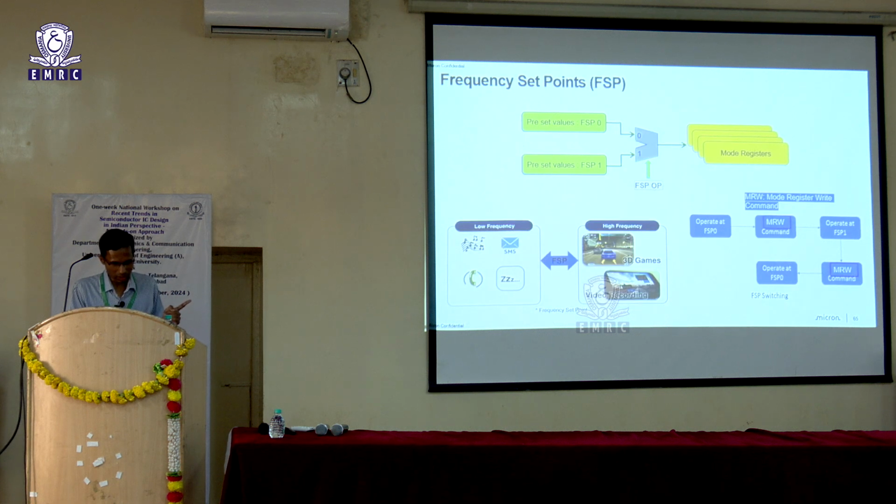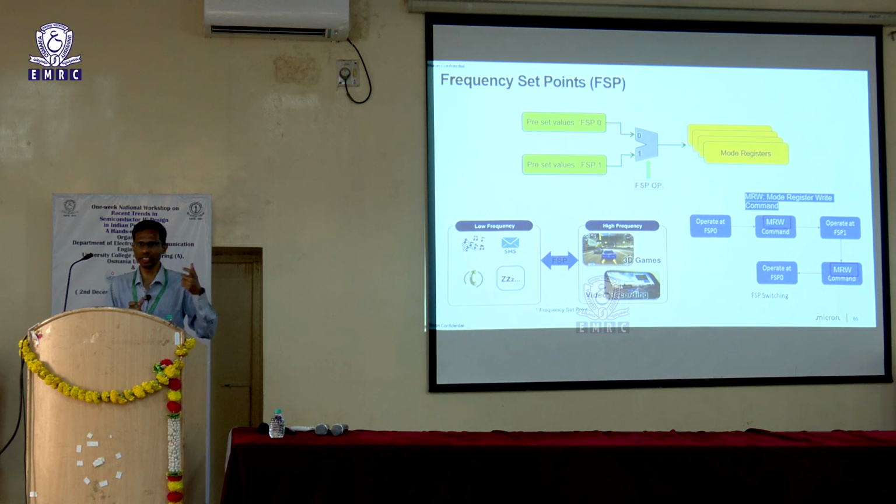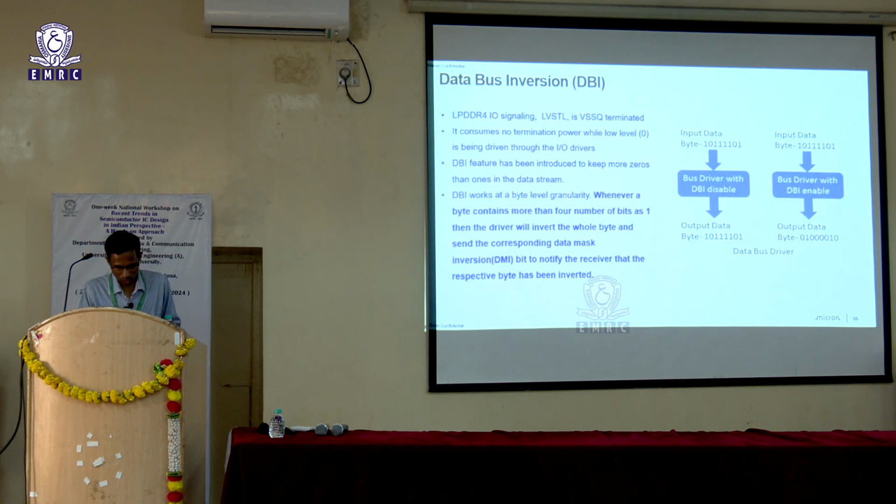I talked about this frequency set point. So, for example, if you are sending out an SMS versus taking a call, those are all typically low frequency operations as opposed to doing a video recording or playing a 3D game. So, those are high frequency. So, you would have 2 different frequency set points, and that is done through mode registers, and we talked about mode registers as being part of your digital design framework there. So, this is where it all ties down to.